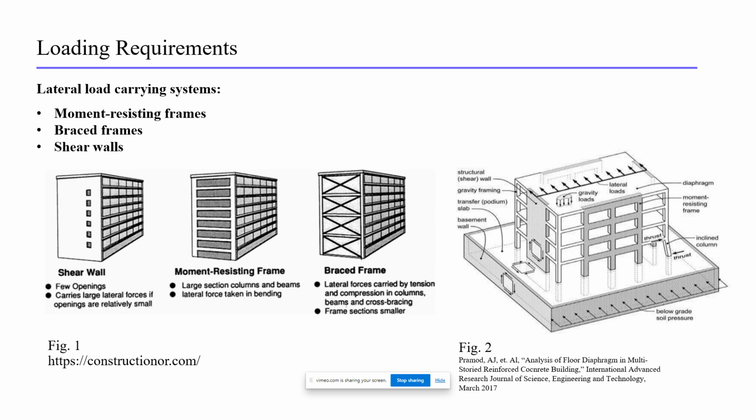Let's go into some detail on that. Here are the primary methods of resisting lateral loads in buildings in Figure 1. You have shear walls. Those are relatively large vertical elements that support lateral loads via in-plane shear, common in building construction. The simplest example of this is framed wood walls in homes, where the shear is carried by the wall sheathing. In larger commercial buildings, that might be an elevator shaft or a stairwell, where you have a monolithic or a block concrete wall in the middle that takes all of that lateral load.